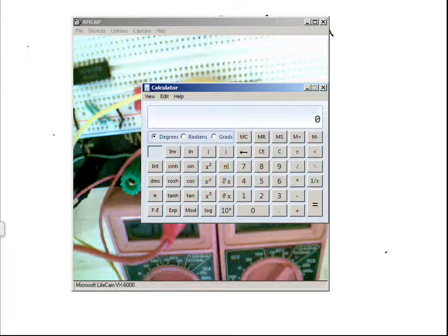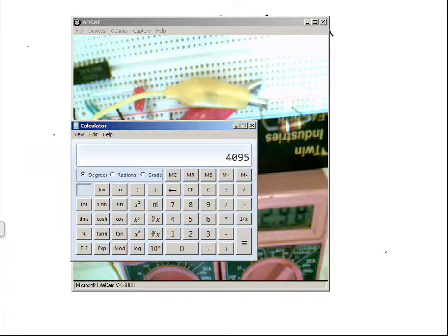So let's come back up here and say 3900, 39 with two zeros, times 0.05 equals 1.95 plus 3900 equals, see, so my resistance there is a little bit high from what it should be according to the markings on it. But the actual numbers read by the meters work out. So you can't always trust the color code. It's going to be close, but it's not necessarily going to be perfect.